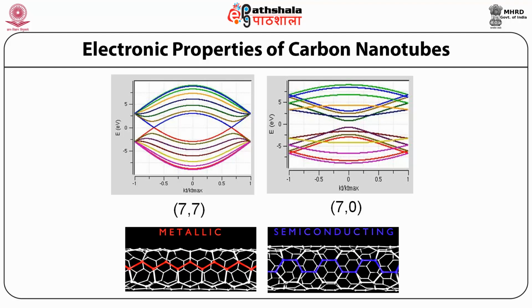There has been considerable practical interest in the conductivity of CNT. CNT with a particular combination of N and M, the structure parameter indicating how much the nanotube is twisted, can be highly conducting and hence can be said to be metallic. Their conductivity has been shown to be a function of their chirality, degree of twisting, as well as their diameter. CNT can be either metallic or semiconducting in their electrical behavior. Conductivity in a multi-wall nanotube is quite complex.